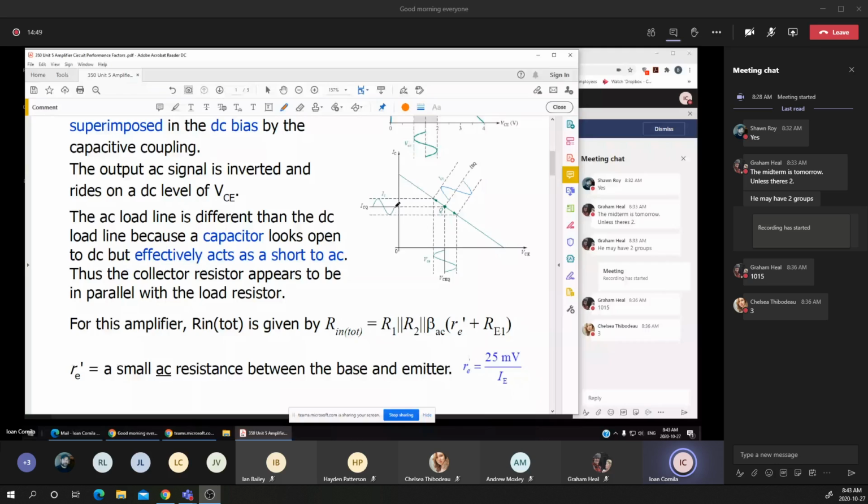It means that I'm getting a gain, or an amplification, in the collector. And in terms of the voltage, again, we'll have the same swing, or the same replica of the input voltage or the input current, except that the collector voltage is 180 degrees out of phase with the input voltage.